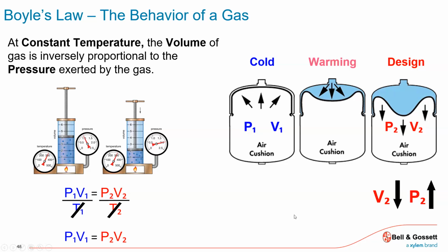So volume goes down, pressure goes up. Why is the volume going down? Because I'm heating the water and water's entering the tank. So that body of gas that I have, that doesn't change. It's separated by that butyl diaphragm, so it's always there. It's just increasing or decreasing in volume based on the water pressing it. And conversely, what happens when I turn the boiler off and the energy starts to dissipate? This spring unloads the water out of the tank, because the water's contracting, shrinking the molecules because it's losing its energy.